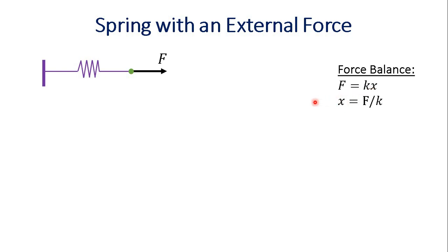Now let me tell you that we do not employ the force balance equation in the context of the minimum potential energy principle. A lot of students make this mistake that they try to find the logic behind the minimum potential energy with the help of this force balance equation. So we are not going to use this equation, and while studying minimum potential energy, you have to literally forget this force balance equation.